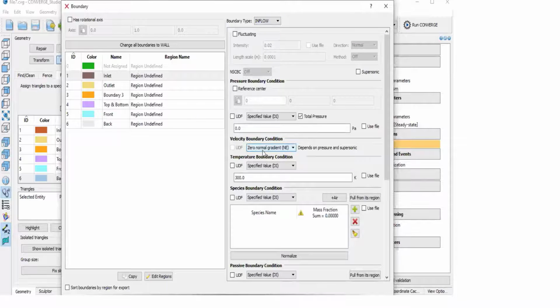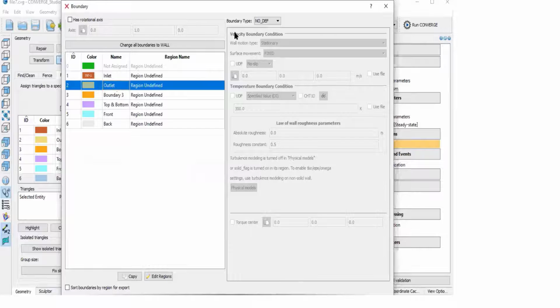Now it will ask a lot of things, okay? Whether you want a total pressure condition at the inlet, or you want velocity to be mentioned, or you want a temperature boundary condition, depending upon the application. Here I will provide the total pressure boundary condition, let's say 110,325 pascals. This is my total inlet pressure. Now it will ask for the region. We have to create the region and initialization. Now for outlet it will be outflow, correct?